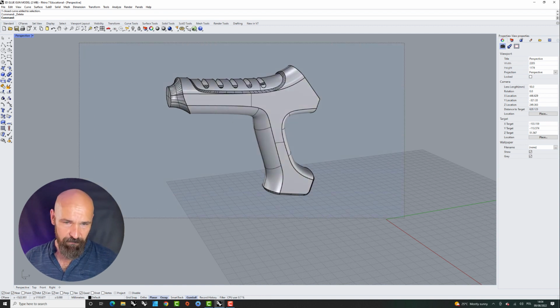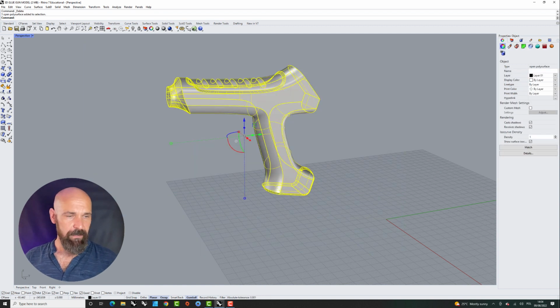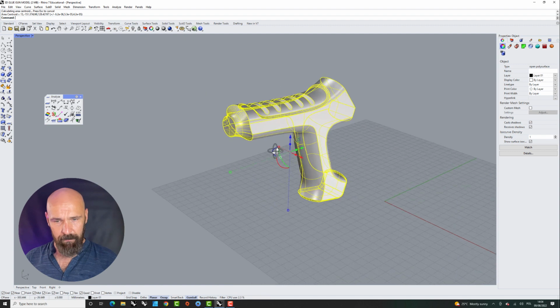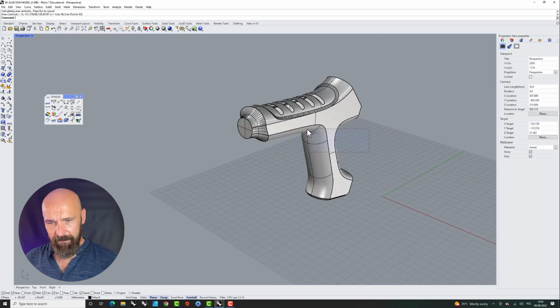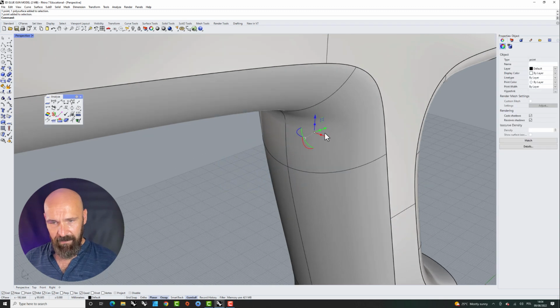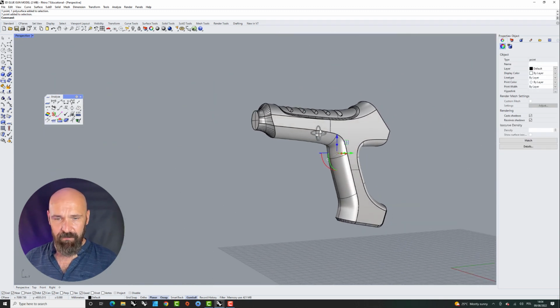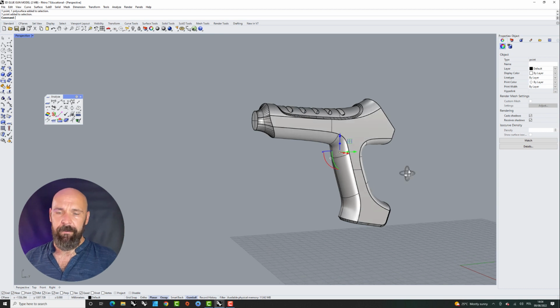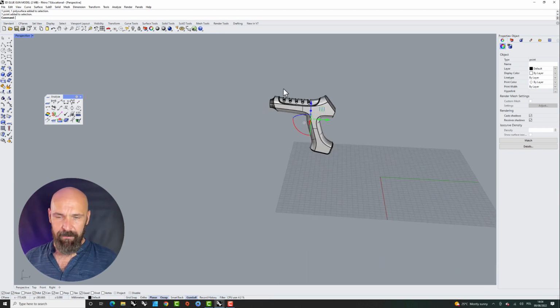If you select the object and you go to the evaluating bar here, analyzing bar, it's enough that you click that command area centroid, and then you can find it there, from right to left. This is the area centroid. That's the exact center of all volume of my glue gun.